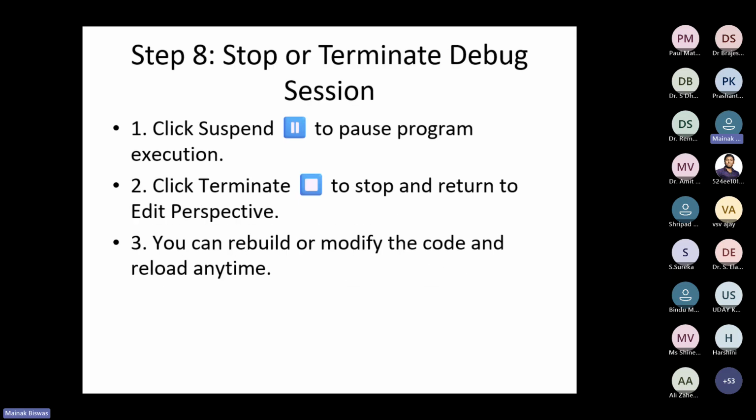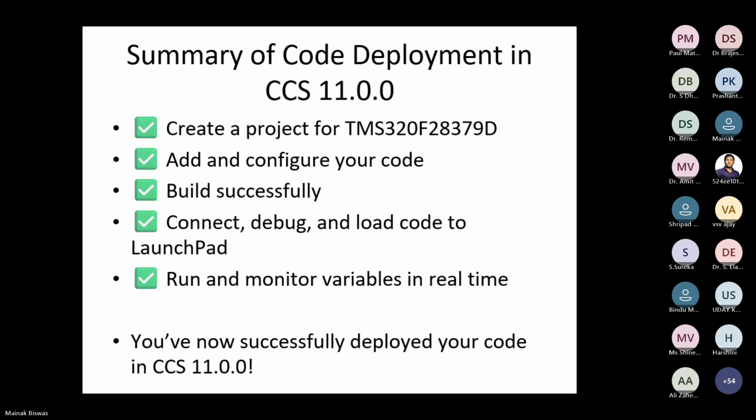To stop or terminate the debug session, click on Suspend, like the pause button, from the execution. Click on Terminate to stop and return to the edit perspective. And you can just rebuild or modify the code, and it will reload anytime. Okay, so the summary of code development, that is the summary I have basically already discussed.